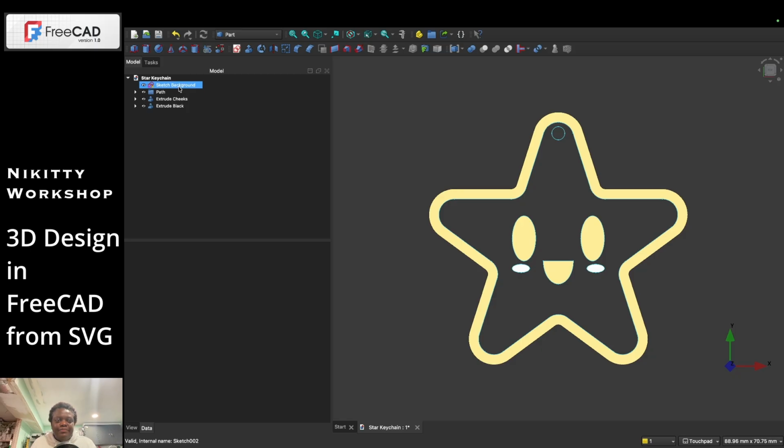Now the background, again, if I did this right, the way that we selected everything else that's empty here except for this spot is going to be extruded because we selected it together as one path. It's going to overlap. Everything else that is selected, it figures it out, and we're going to extrude that part as a solid object. Already divided. You don't have to go through and cut. You don't have to do any boolean, which is why when I set up the SVG file, we make sure to do it beforehand because we want to have this double-sided all the way through.